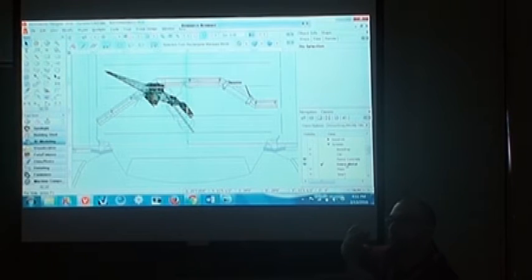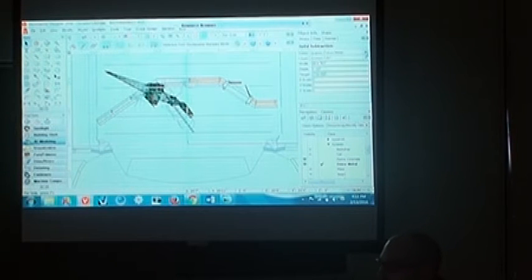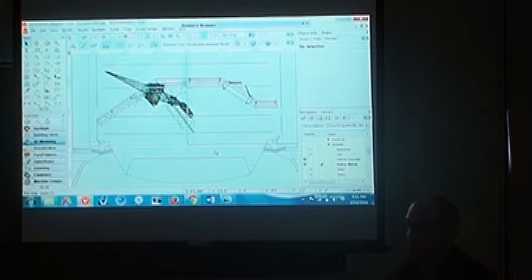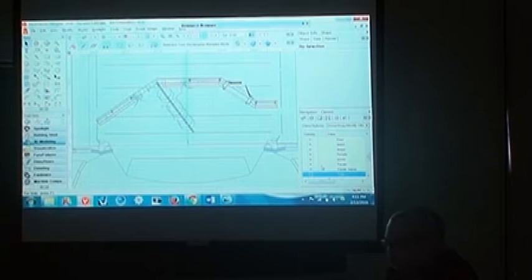Because you do that, it automatically creates that hierarchical view, and if you go to assign an object to a class, it will go through that hierarchy as well. So if you're doing something with a lot of classes, something very 3D intensive like this, that's a handy way to get your classes to organize into that menu structure by using a hyphen in the name. I don't think I mentioned that in my tips.